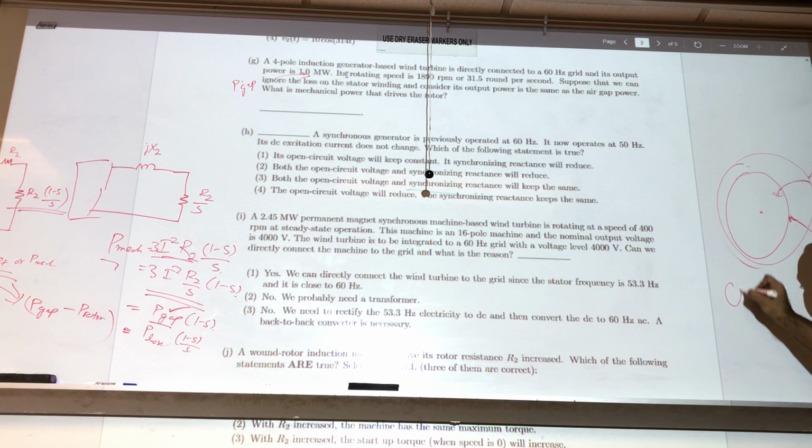If we have a source here, which is V volts, an inductor here, a resistance here, and a load here, then to find the power, if you have an input power of P in and this is the P out, then P out should equal P input minus the loss at this place, right? Minus I square R, right?